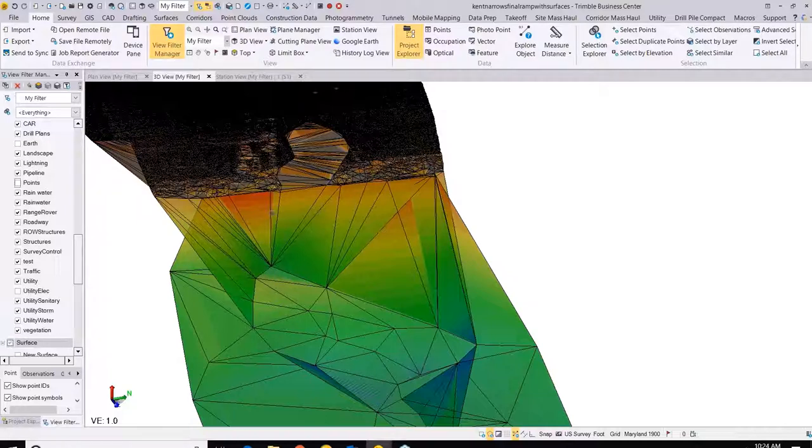You'll hit that, establish your survey, and then you'll know the tidal differences. I know lots of tidal ranges are different. There can be a 15-foot one, there can be a 20-foot one, and many different factors: the wind, is there a storm coming in? So you're going to really watch what you're doing out there when you're doing that kind of survey, if that answers Mark's question.